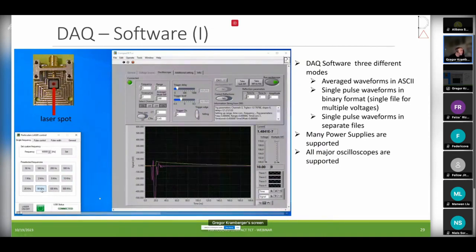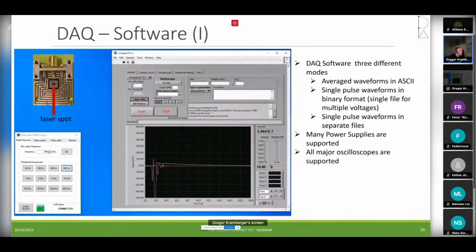Now you see, this is the interesting thing. If you increase the frequency, you don't see any change, and the reason for that is very simple, because what you're observing is a single pulse. What would change if you look at the longer time scale would just be the number of these signals. But each signal should be independent of the frequency, of course. You can test this if you have a high rate environment. So if you have pulses in your experiment, or if you want to use it for some specific study, you can set it up to, I think, 1 megahertz, which can be used electronically. If you want to have high frequency, you need to use an external trigger.